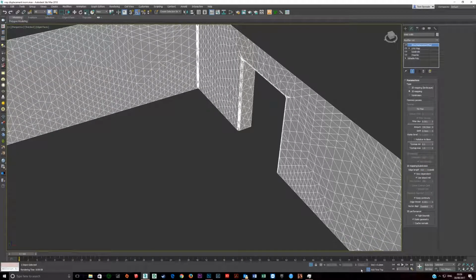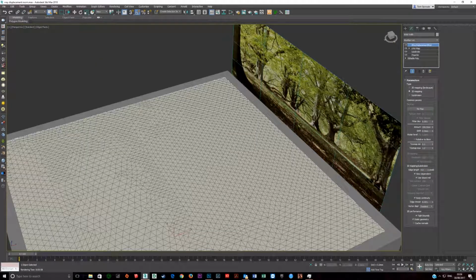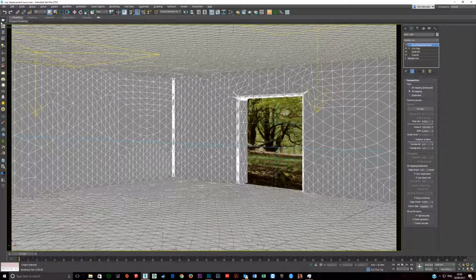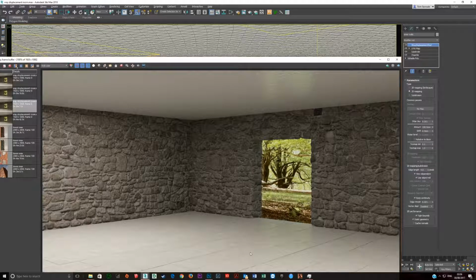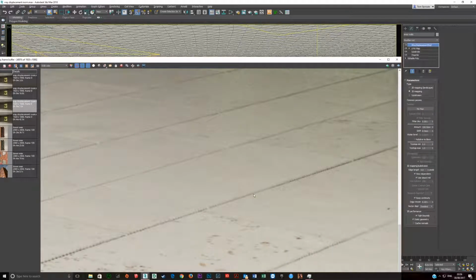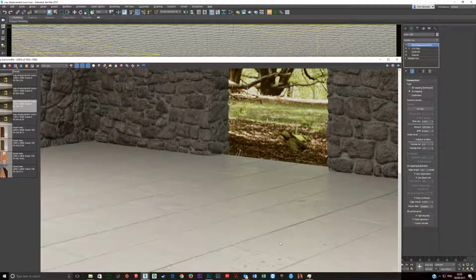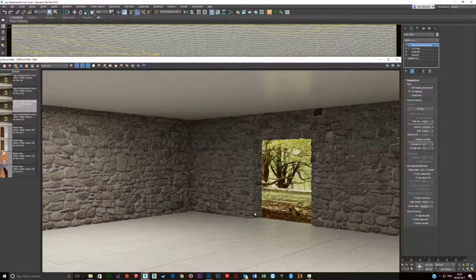But at the same time, if you look at the render, if I click here on the V-Ray frame buffer, see this floor? This floor has all these jagged edges, and those jagged edges are caused by this pixels being at 4. So if I set that to 3, then those jagged edges should disappear. So let's try that.